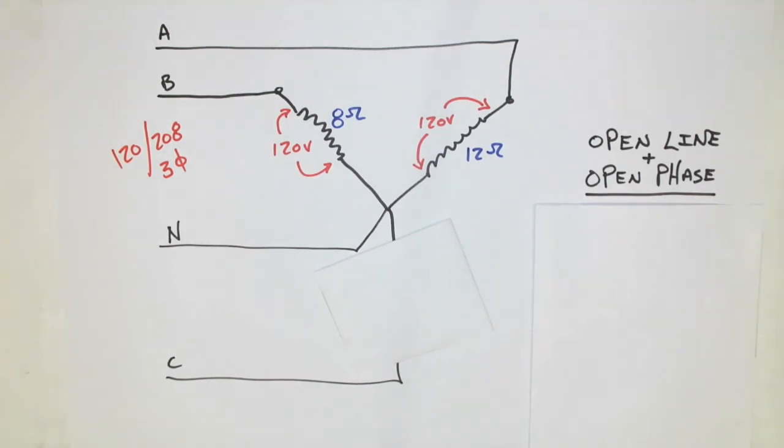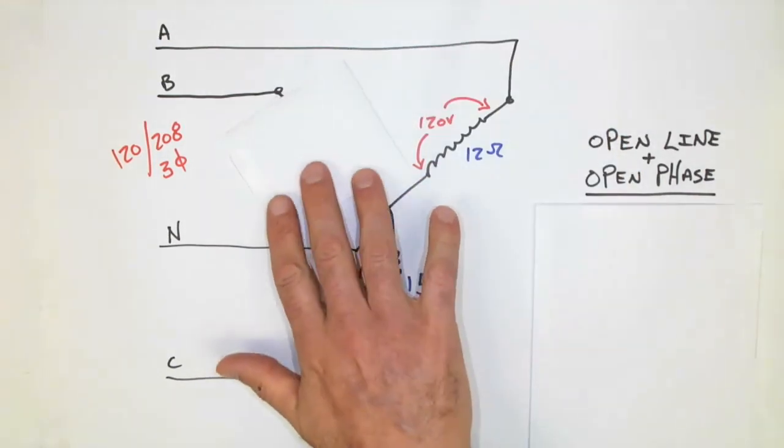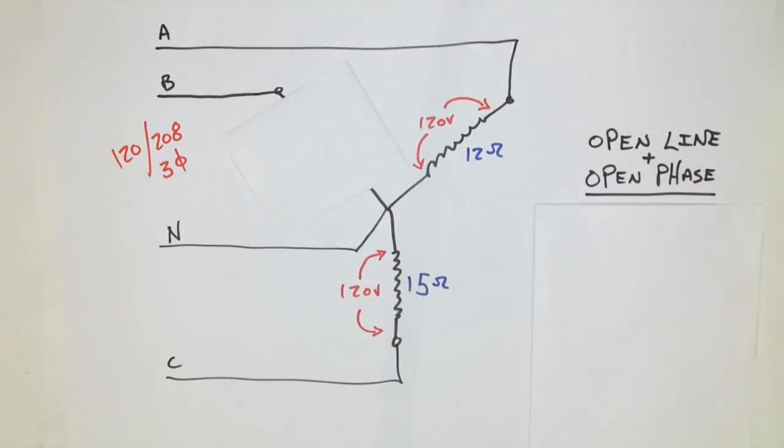And this is what happens in a large commercial or institutional setting where loads are continually being turned on or off as people utilize the facility. Lights going on, lights going off, motors turning on, motors turning off means that the load is continually varying on all three phases. Since we have a neutral, if at any time the entire phase load is dropped to zero because it so happens that there is no loads energized at that moment, the remaining two phases see no effect.